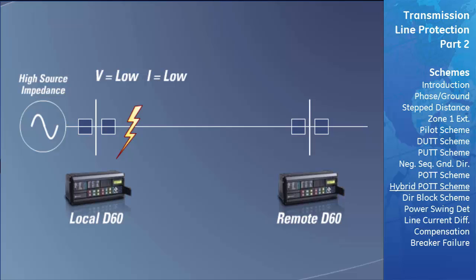Also, the zero sequence and negative sequence current will be almost zero. Therefore, the forward and reverse ground directional overcurrent elements will not operate. Even though none of the distance relay's protection elements have picked up, the faulted line still needs to be cleared. The weak in-feed feature of advanced distance relays can detect this condition and correctly trip the relay.